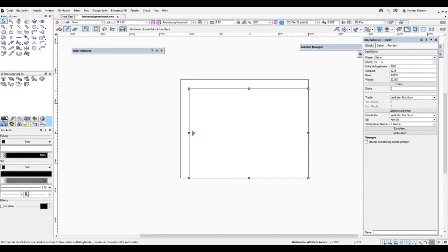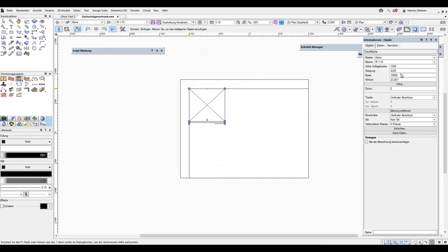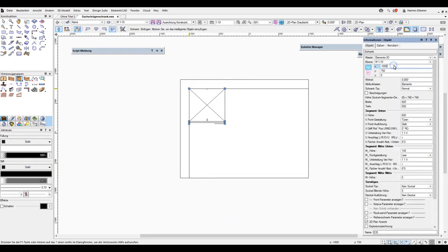In any case, we can now insert a cabinet. I click on the back corner. I confirm with OK, and can already enter a distance of 50 mm for the front panel and -20 for the setback in the Y direction. The depth of the cabinet in the body is 500 mm. We can also set the width here, and here we have a width of 1500 mm for the external dimensions of the cabinet.